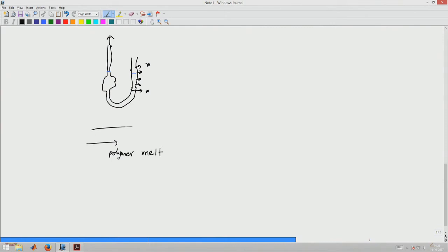So, if polymer melt is flowing through some die or some device, is it possible for us to tap into it, take some amount of melt out, pass it through some other device and then measure viscosity? So, it is for inline, online measurement of viscosity. What is done in this case is that it is possible to put the fluid back, so that it is basically an online device.